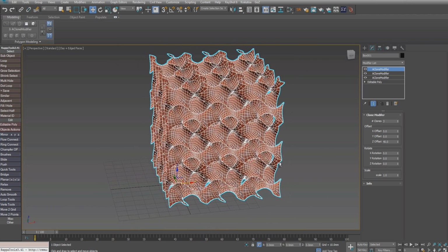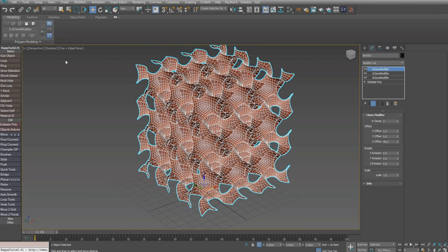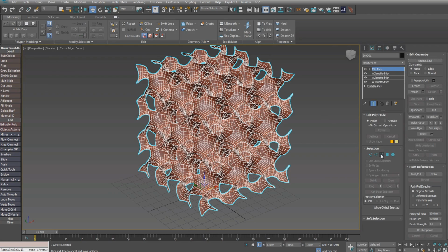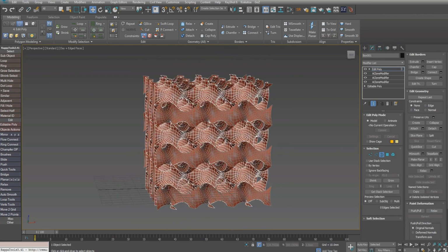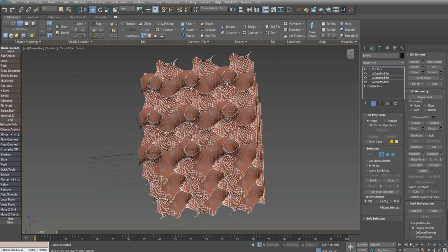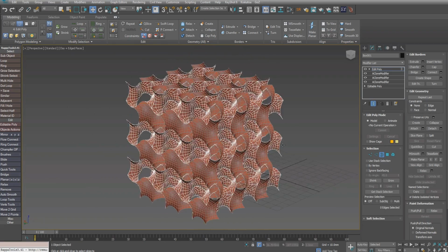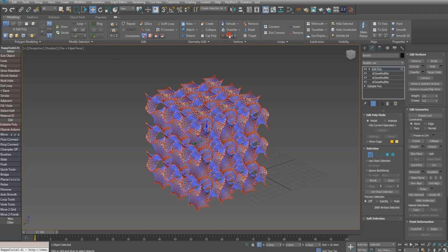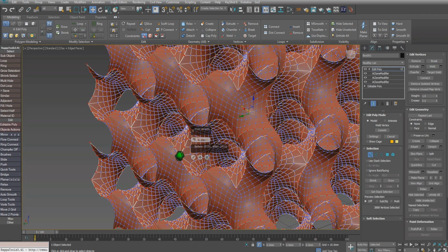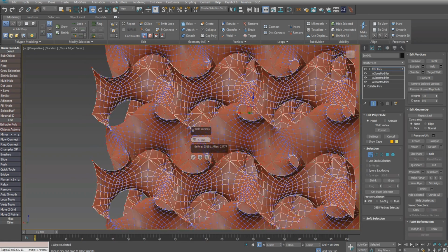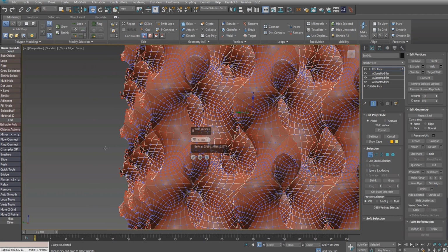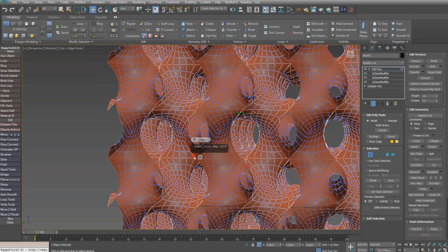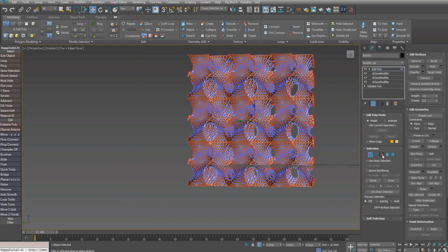And you could see that that has created a triply periodic, perfectly aligned gyroid here. Okay, so this is all clones of the original. Now, if I wanted to 3D print this, my procedure would be the same as before. However, I would operate on all of the clones rather than just the one object. So I'm in border mode, and again, I'll box select all of the borders here, and holding down Shift, I will go to vertex level and Shift click on Weld to bring up the caddy, and do the same welding procedure. 1.1 looks like it might have done the trick, so I'll accept that.